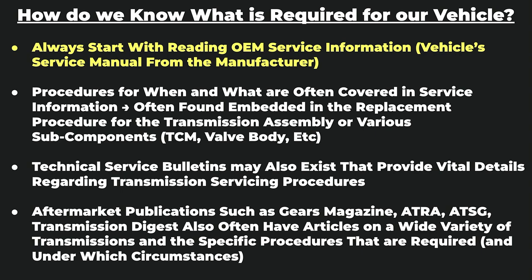It's also important to remember that where they put the information in the service manual can vary depending on the vehicle manufacturer. I have always found it fairly reliable to look at the replacement procedure for the transmission assembly, and most of the time that will give you the overall map of what different types of relearns or programming scenarios might be required for the specific vehicle, because replacement of the entire assembly is by far the most extreme repair out of all that are possible, right? So just something to keep in mind if you're trying to imagine where you would start in the service manual to find the information.